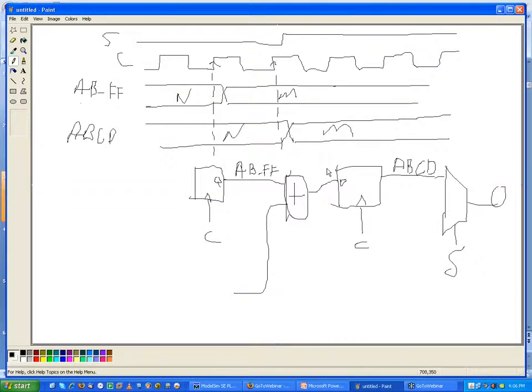Would it meet it? Well, the nice thing is you're not going to have to keep track of all that as long as you're using sequential logic that's clocked and the flip-flops are using the same clock, because the tools will actually do that for you. And if you meet timing analysis, and that's very important that you always meet your timing analysis so that you can guarantee that this thing will always work in this manner like we've done here. This is what we want to do. So we'll talk about that a little bit more during the lecture. Okay, shall I continue on, or is there another question?